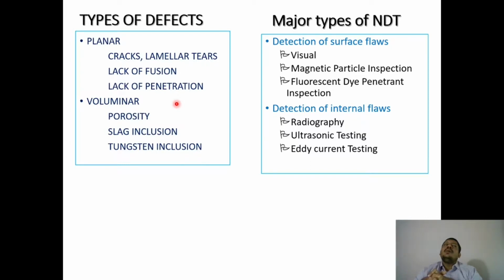When you studied material science, you might have studied the process called tensile testing, where the material is prepared to its specification, ASTM standards, and connected to a UTM, and elongated. The material moves from the elastic limit into the plastic limit, and finally the material breaks.